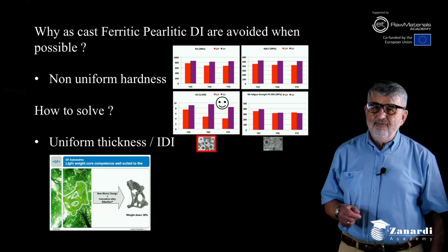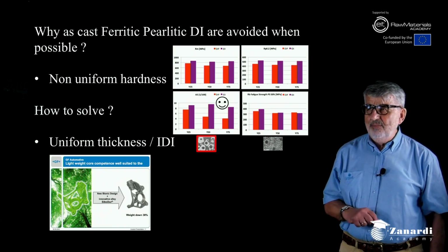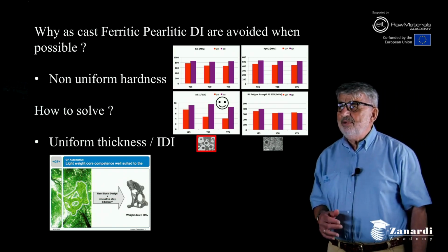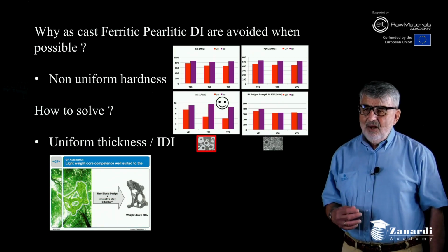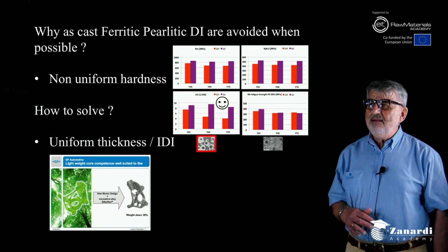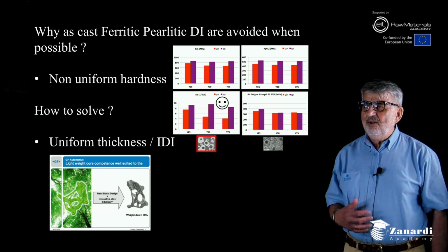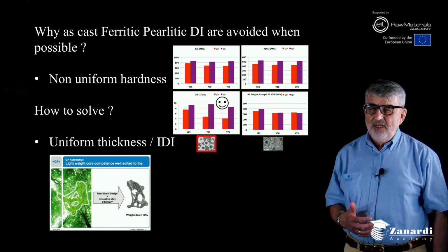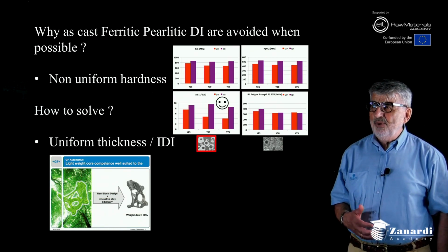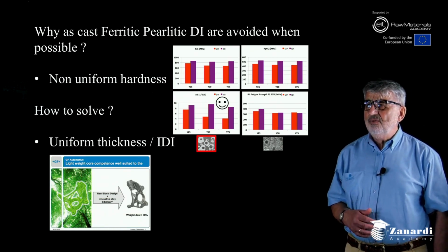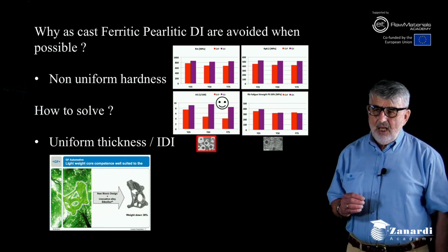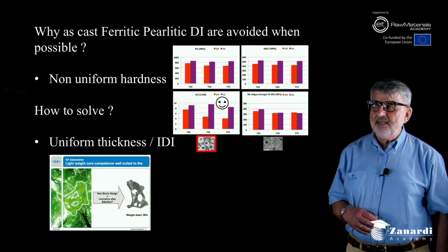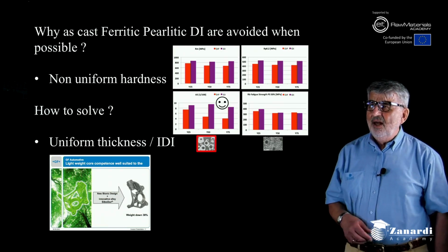In this way, we avoid the martensite because the salt bath is above the martensite start temperature, and we get fine pearlite connected with proeutectoid ferrite that gives us superior strength, superior elongation, and most of all, uniform properties in different wall thicknesses, say 25, 50, or 75